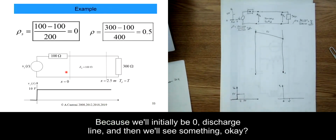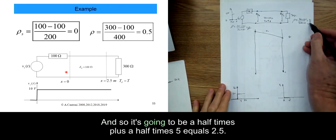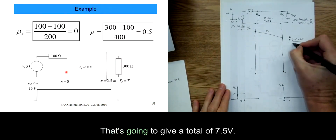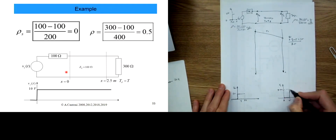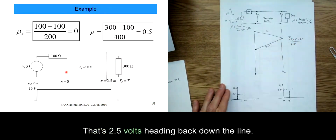VL, because we'll initially be 0, discharged line, and then we'll see something, okay? So that's going to be the 5 volts arriving plus what's reflected. And so it's going to be a half times 5 equals 2.5, and it's going to give a total of 7.5 volts. So initially it's going to go a little bit high, 7.5 volts, right? Okay. Now that's going to be heading back down the line like that. So it's 2.5 volts heading back down the line.